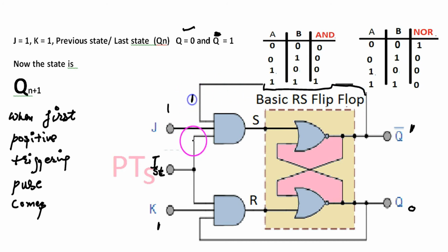So 1 comes here, this is 1, 1 output, 0 is here and it gives 0. So this line at 1, this gives 0, 0 at here, that becomes 0. So 0 comes here, 0, 0 is 1, 1 comes here. Okay, the 1 comes here, 1, 1 is 0. So this is again a stable state, 0, 1.